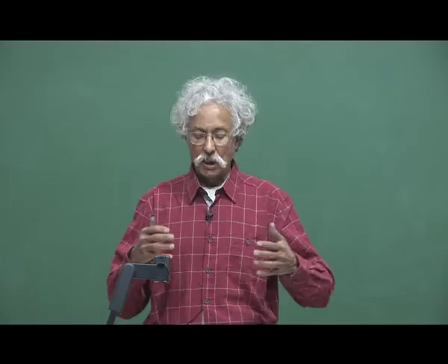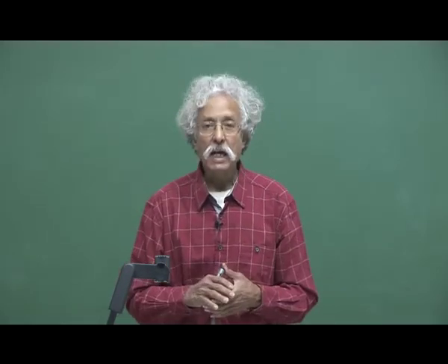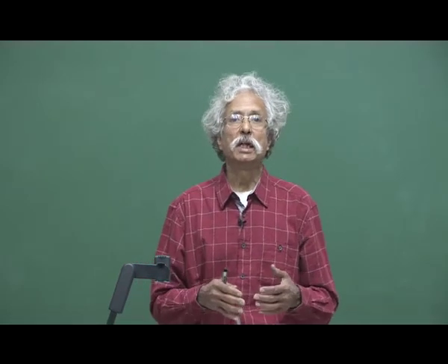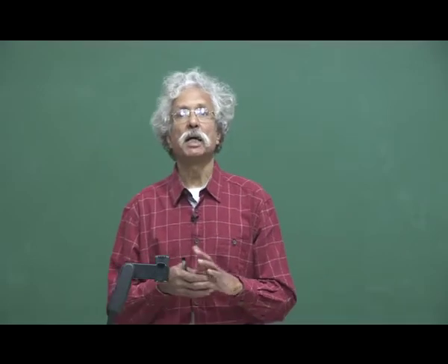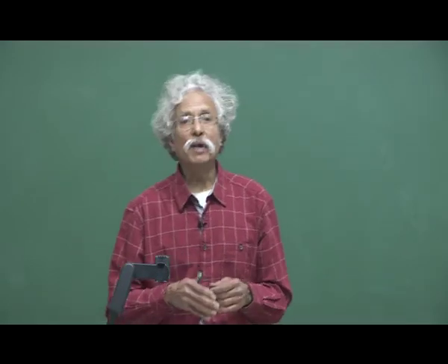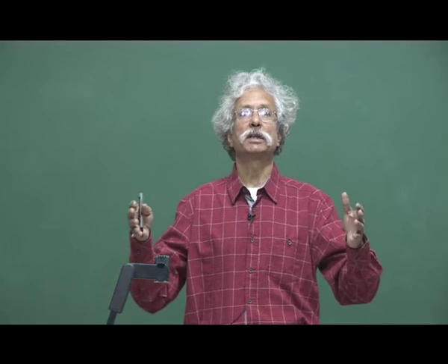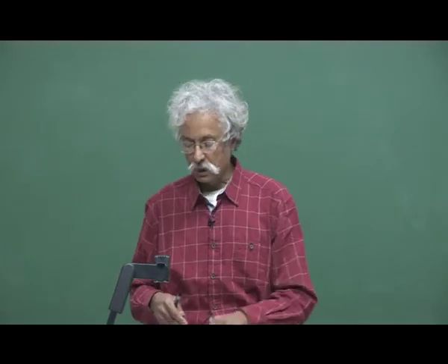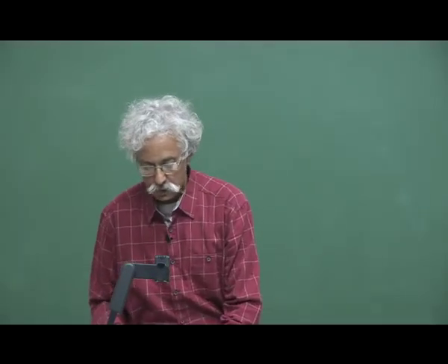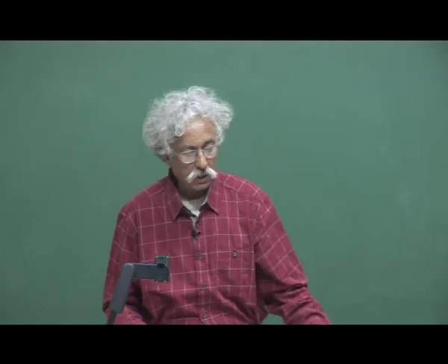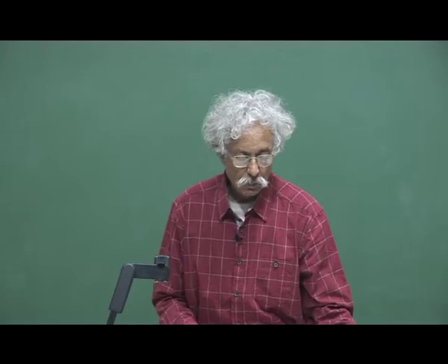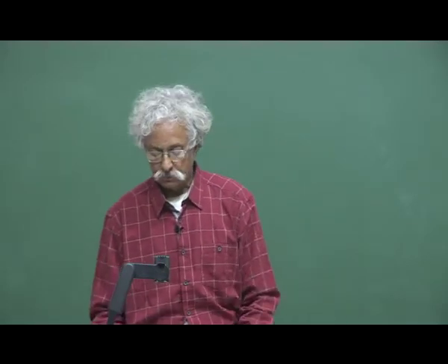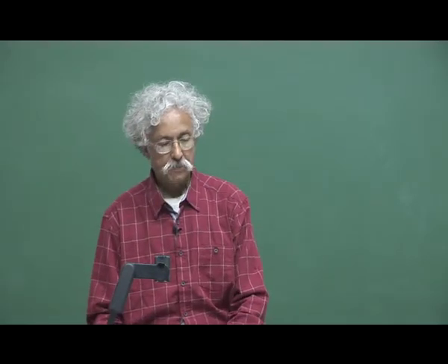So, I can measure very sensitive currents through this, and I have two examples in which I have seen how to convert a galvanometer into an ammeter, which will measure currents passing through the circuit, or a voltmeter to measure the potential differences across different points in an electronic circuit. So, these two examples tell us how torques in the presence of magnetic fields can be used to measure currents and potential differences in a circuit.